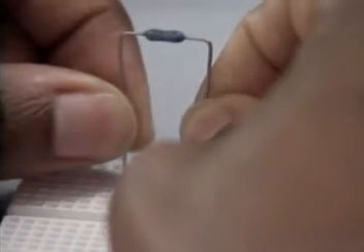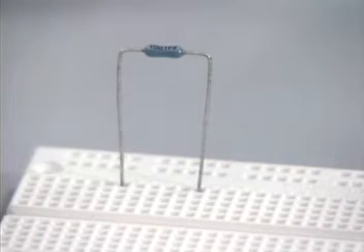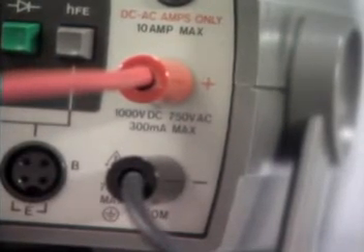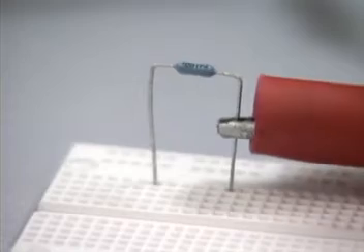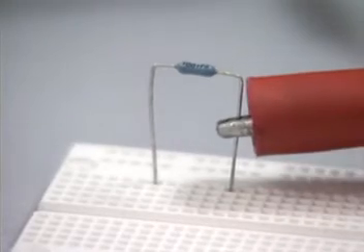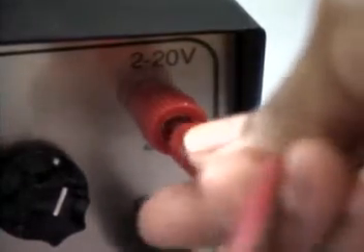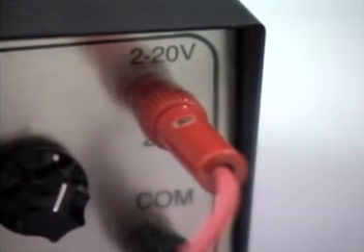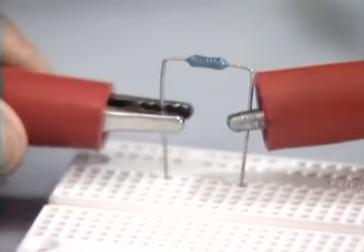Returning to the circuit, insert the resistor's actual leads into holes for each of the 5 common contacts. Be sure to separate the leads by 5 or 6 holes for proper spacing. Next, attach the red positive lead into the positive terminal of the ammeter. After that, connect the clip end of the red lead to the right side of the resistor. Using a second red lead, attach the plug end of this wire to the positive terminal of the power supply and the remaining clip end to the left side of the resistor.